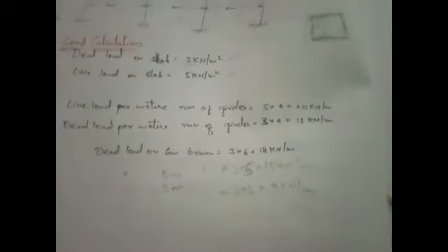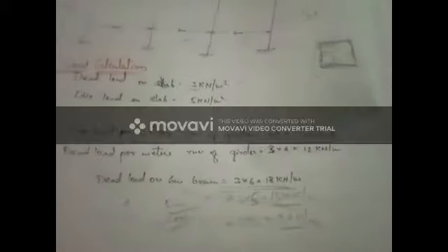And when we are analyzing the process, that is when we go for distributing the moments in the cyclic process or moment distribution table, we are supposed to keenly observe. If the beam is having 5 meter span, then we are supposed to give the load of this, and if the beam is 3 meter span, then we are supposed to give the dead load as this. Okay, as here we have all the beams the same, so there is no problem with respect to this, we will consider only this section. Okay, now the process of load distribution is done.